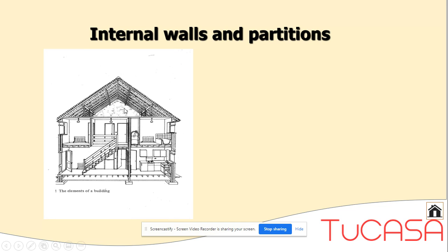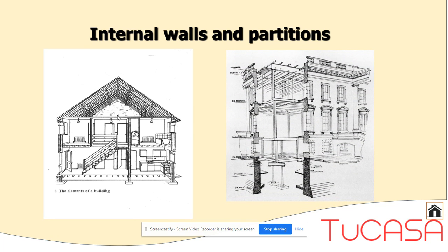This might be a terrace property where you've got purlins spanning between different party walls to provide the basic load-bearing structure for the roof. And in this cutaway, planning various internal alterations with beams and columns behind an existing facade, you've got to make various allowances for transferring loads so that everything is taken safely down to ground level.